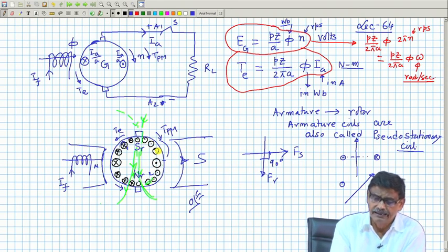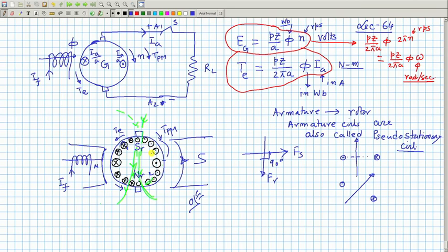So mind you, it is like this, and therefore, in case of DC machine, the number of poles of stator and rotor must be the same, and not only that, we can draw, knowing whether it is operating as a generator or motor, the current distribution by applying the right hand rule, and it is all DC. Therefore, direction of EMFs decides the direction of the current, no question of any power factor coming in between. Therefore, the distribution of current, I mean polarity of the currents under north and south pole, is fixed once it is known whether it is a generator or motor.